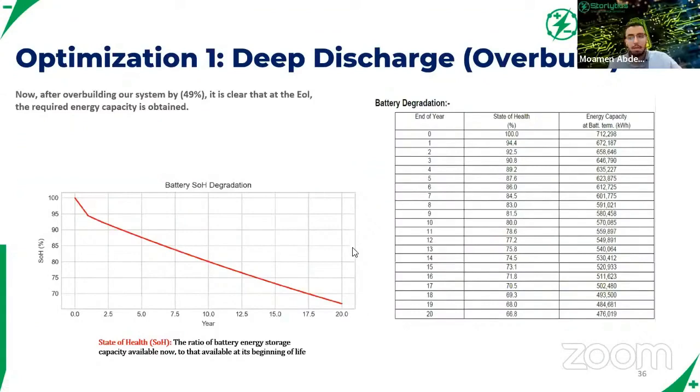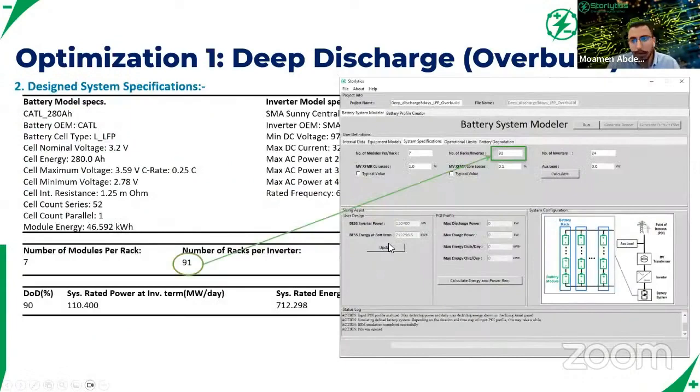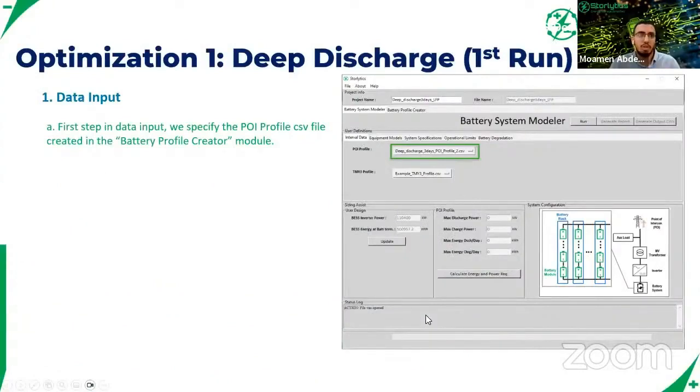I can add a quick update for our next version. This is regarding our software. In our next version, we will have enclosure models that allow the user to simulate different auxiliary loads. You will be able to define your enclosure model and enclosure type, along with the TMY profile, which allows the user to input the ambient temperature of the site where the energy storage system will be installed.